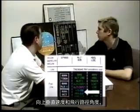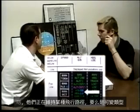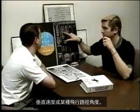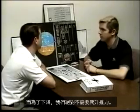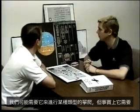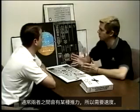Vertical speed and flight path angle. Well, they're maintaining some kind of flight path, either a variable type of vertical speed or some kind of flight path angle. To do that, we don't need just idle thrust. It may take idle thrust, but we don't know that we need it. And to descend, we definitely don't need climb thrust. We may need it for some type of climb, but the fact of the matter is it needs some kind of thrust in between typically, so it's going to need speed.